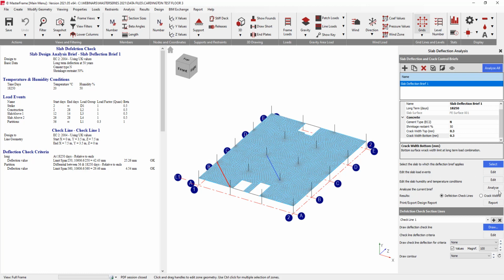So those are the extents of our inputs, and we're actually now ready to go ahead and do an analysis. And in fact, an analysis already exists on this, but I'm going to push the button again to do it, to show you the performance that you can expect, obviously in this case dealing with a single slab. So the analysis is extremely intense in that with each time event, the cracked nature of each element in the slab needs to be assessed.